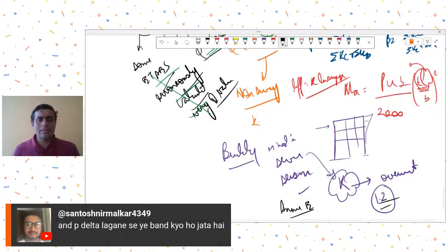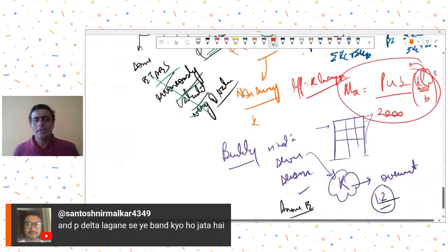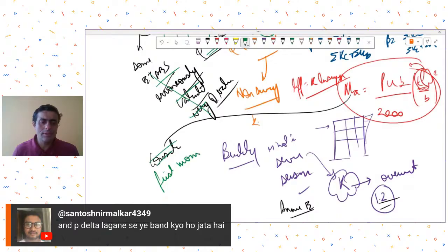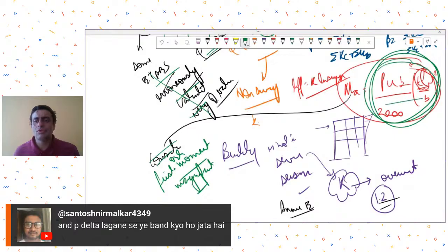So the answer is that these additional moments basically are called the first order moment magnification process, where we are not analyzing for the actual deformed geometry, and because we are not analyzing the structure for actual deformed geometry, we are artificially magnifying the moments by these formulae.